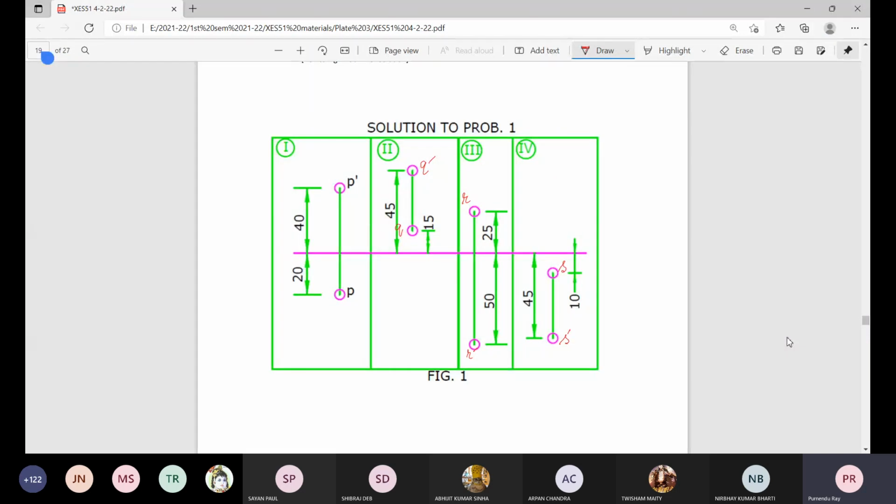Now these right angles that we are making are not through a protractor or the standard school geometrical construction methods. Simply use 2 set squares or the diagonal scale where a 90-degree arrow is there, and you can directly draw these perpendicular lines. All these lines will be drawn on this XY. These lines are perpendicular to the XY line or ground line.